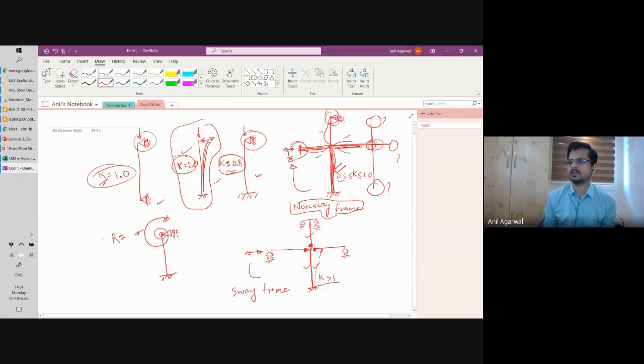You can't have a beam that is very flexible, because a beam has to offer some flexural resistance to the loads acting on it. So if you have a pin connection, no matter how stiff the beam is, it is not transferring any moment to the column, or resisting the rotation of the column. It will not mind if the column wants to rotate. In that kind of situation, you are closer to 1, as long as the bottom is also pin connected. But here the bottom is fixed, so you will end up being closer to 0.7.